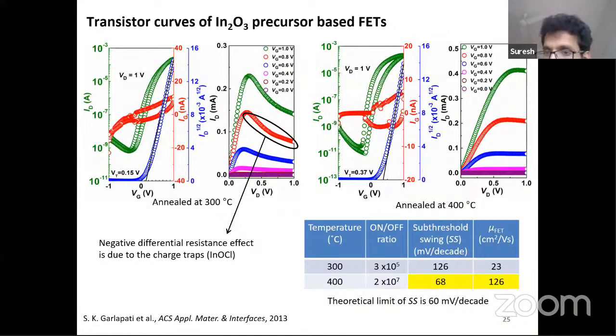If I characterize the 400 degrees centigrade annealed samples as well, there we can see a nice graph. Also in the IV curves, we can see an increase in the current and a saturation region. This is the ideal behavior of a transistor. We get this because the indium oxide is now completely pure indium oxide, the grain size is very large, and the interface scattering is also very low. That is leading to the large current and low scattering at the interface.